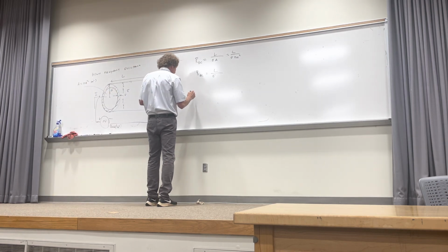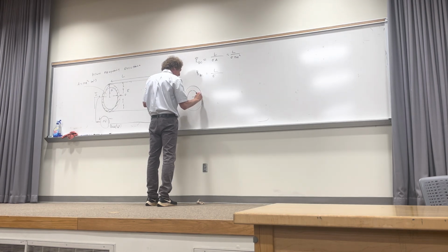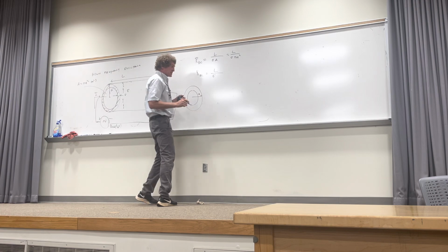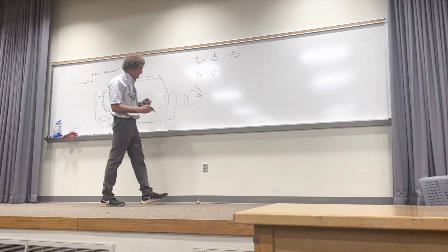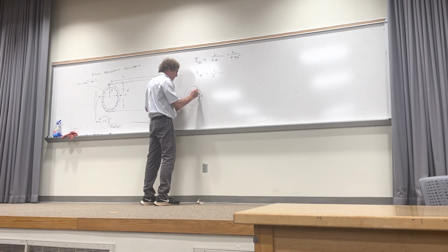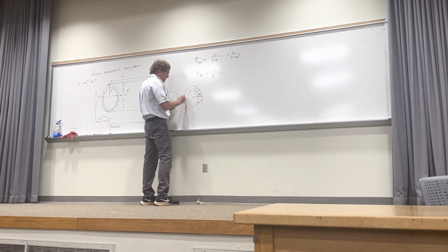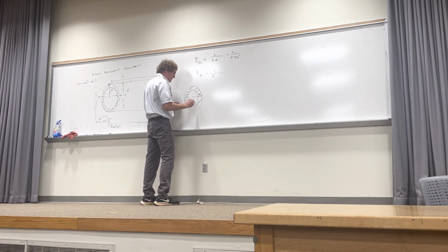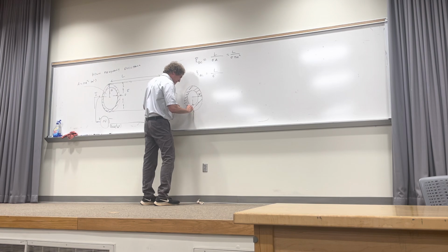So when you look at this, now when we look at the cross-section of the wire, that the current's gonna actually flow, and I want you to see this. Before, I used the entire cross-section of pi A squared, but now I want this cross-section of the wire, and this is simply one skin depth thick.